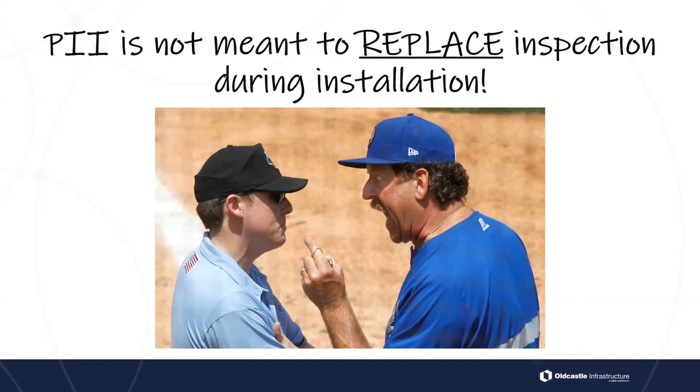Post-installation inspection is not meant to replace inspection during installation. We still want to make sure that we've got inspectors out on the site ensuring that the pipe is being installed correctly, that the pipe's being homed correctly, that it's being backfilled correctly, that it's being bedded properly. We want to make sure that this is being done during construction. Post-installation inspection is not a replacement for that, right? We still want to have inspectors out on the job site.